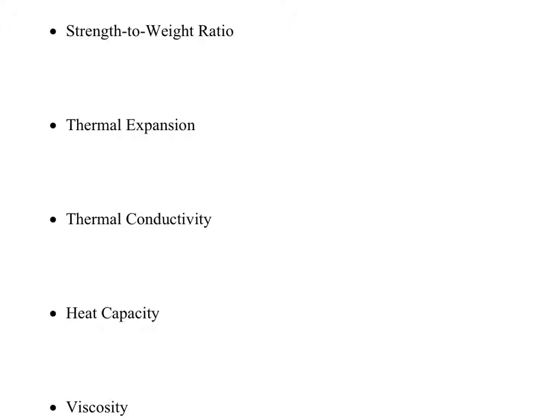Thermal conductivity. These windows are not good at insulating against thermal conductivity. A lot of heat is lost because they're not really good like double pane windows. Double pane windows usually have argon gas between them. Air or argon. Usually argon has a lower thermal conductivity value. It acts as like an insulation or a barrier. Heat does not travel through air very easily. It travels through metal easily, through glass easily. So thermal conductivity is the material property.